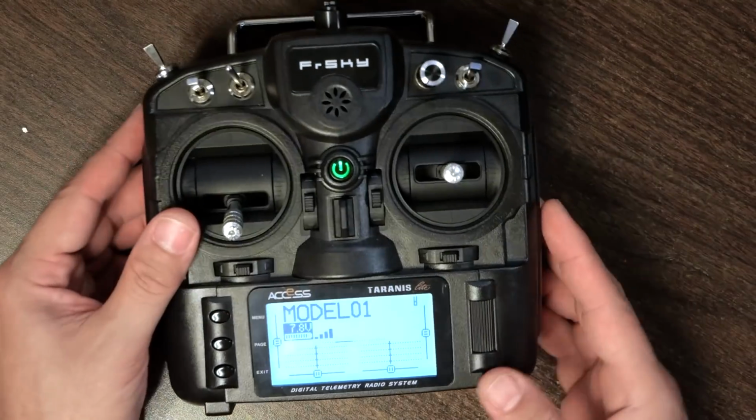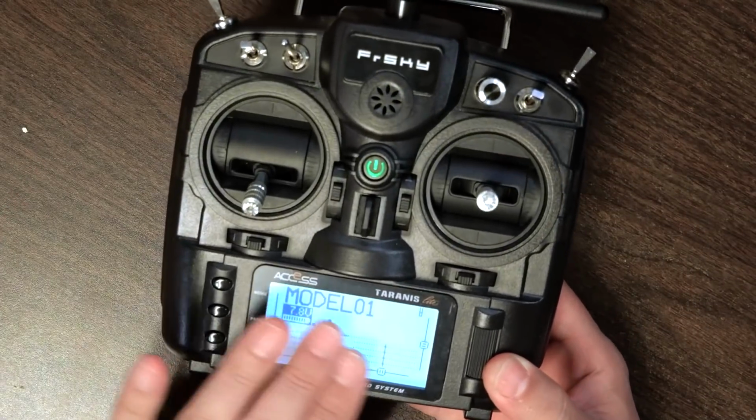What kind of data would it want to send back? A great example of what telemetry can send is your battery voltage. Your battery voltage lets you know when you're about to kill your battery and you need to land and change to a new battery and stop flying. Well, the flight controller has an on-screen display that shows information like that in your goggles, and that's fine, but sometimes it's nice to have that information on the controller as well. Maybe you don't want that information in your goggles. Maybe you want to see it on this screen here. Telemetry is how you can do that.